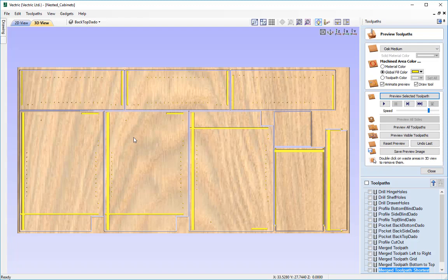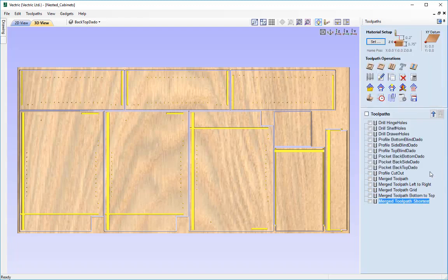And then once you've gone ahead and created the toolpath, you can save those in exactly the same method. As the merge toolpaths only enable you to combine toolpaths that use the same tool, we won't have any issues where you have to have an automatic tool changer or a specific post processor that enables you to pause, so you can change the tool manually mid toolpath.